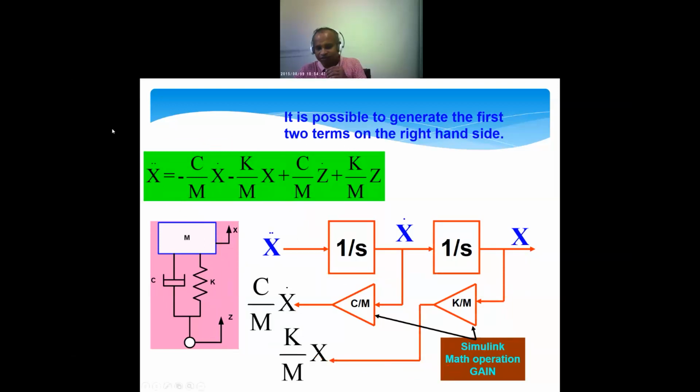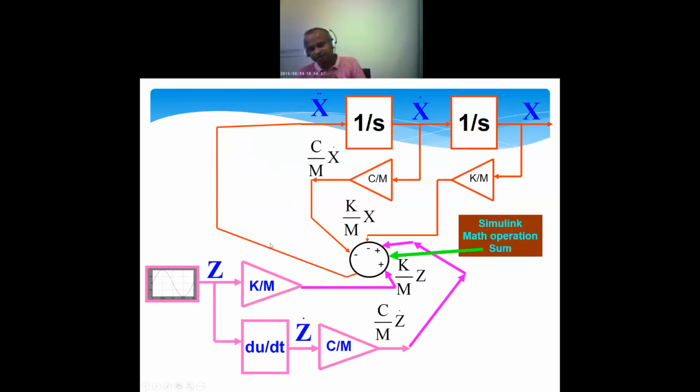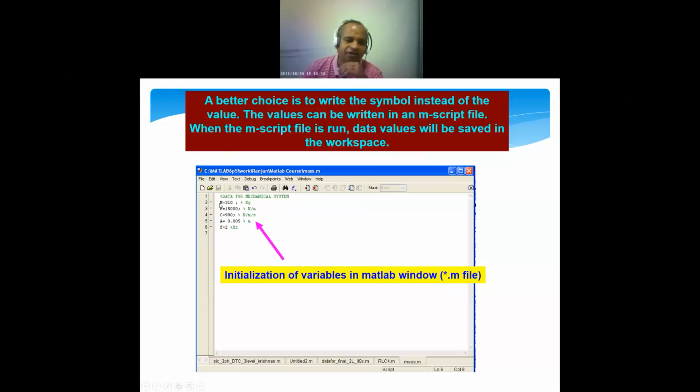And then connecting everything, this is another part of the system we made, and then the complete unit is simulated here. So the x dot is nothing but 2 integrated, then this is your minus, minus, plus, plus. And you can see that the parameters m, k, c, a, and f are defined in MATLAB, in the workspace, and then you will get all the parameters here.